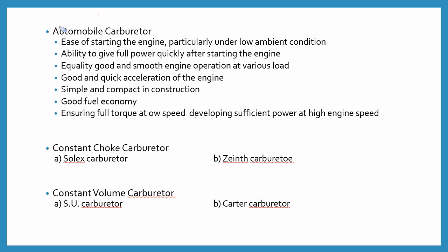Next is the constant vacuum carburetor. When we talk about the constant vacuum carburetor, the air and fuel flow areas are varied as per the demand on the engine, while the vacuum is maintained the same. The SU carburetor and the Carter carburetor are classified as constant vacuum carburetors.